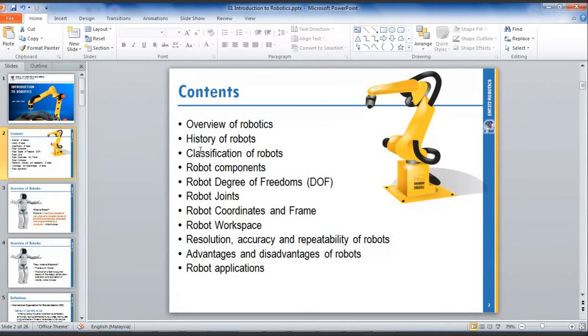and then we just multiply between the matrices. So the calculation process is longer. The DH method tries to simplify, so we can calculate shorter compared to homogeneous transformation matrix.